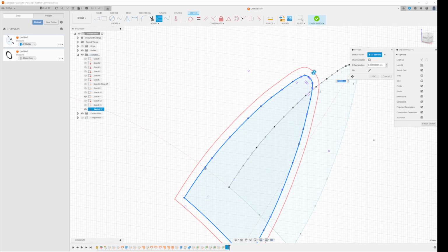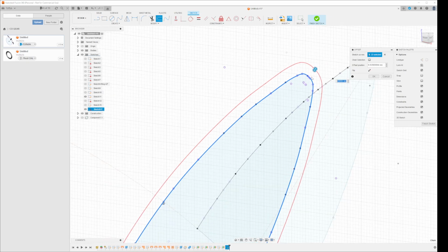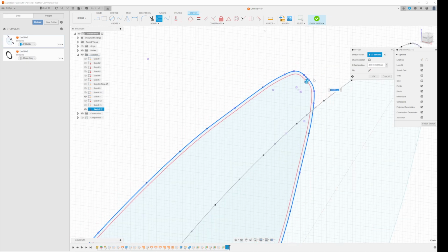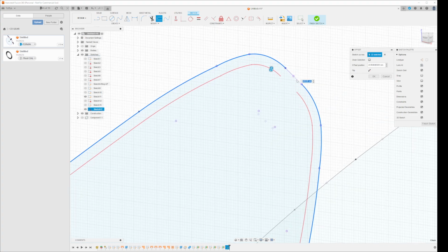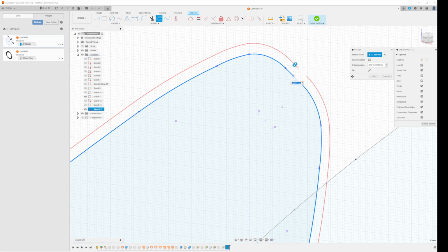So basically what this does is it shows you that because you're trying to make an offset line and you have it like here, barely offset, if this offset line cannot continue properly to the next point, it will give an error. So if I'm here and I select this, you see now it errors out because it cannot reach the line beneath because there is actually no relation from there to there.